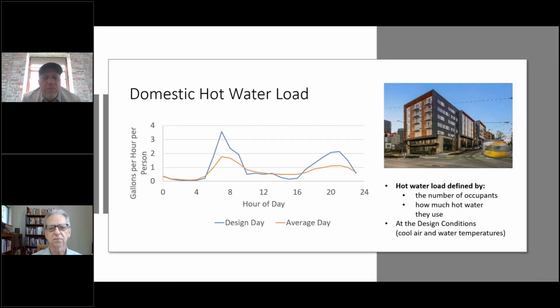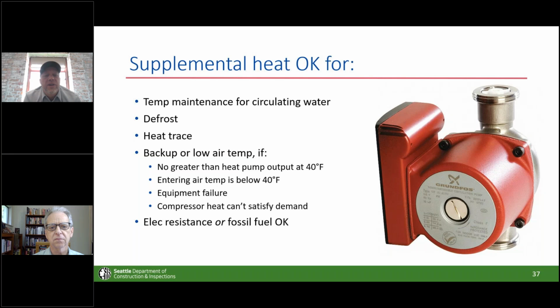Yeah, I would maybe just go back one point to make: the freeze protection is really important. In the Seattle climate, we get a week of freeze, and you have to really be thinking about that, because I've seen heat pumps crack their heat exchangers. So we've got heat trace on all the distribution, but you have to extend it inside of the heat pump and run it around. So that's an important piece. Manufacturers should be pretty dialed into that. But the freeze is real when the heat pumps are sitting outside.